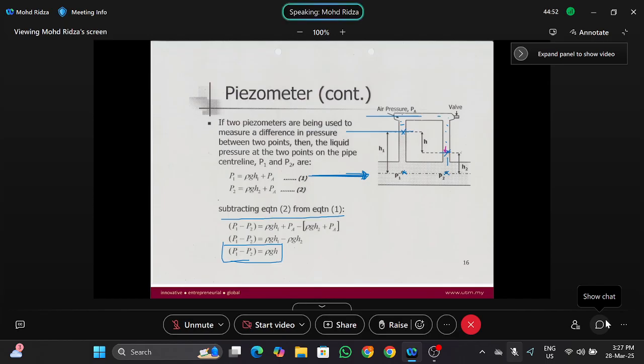But the concept is the same. This concept is very simple. The pressure at some point must be the same as the pressure at a point where you know the value. In this case, PA plus rho g H, plus rho g H. Why plus? Because we are going deeper. If you're going to a higher elevation, you minus. Don't forget that. As you go deeper, the pressure will increase, so you plus. As you go higher, the pressure will decrease, so you minus.